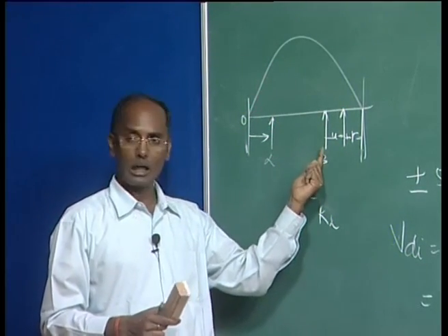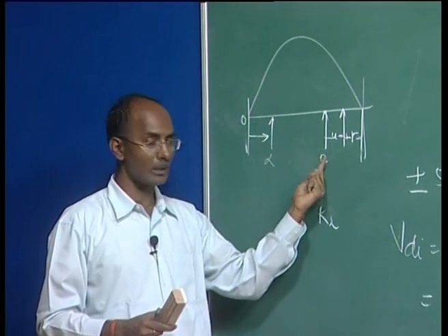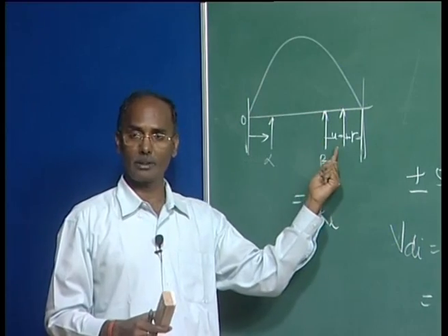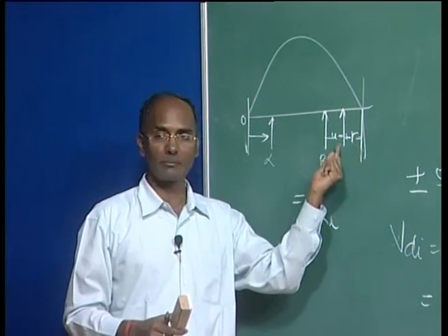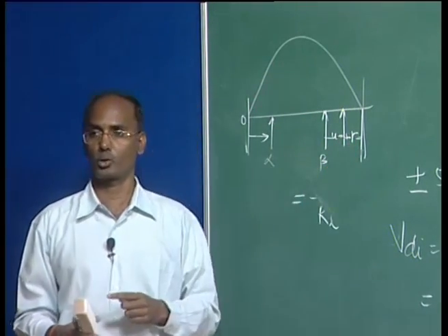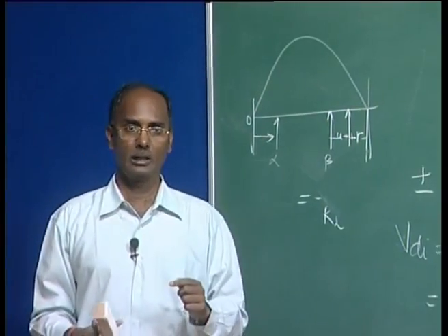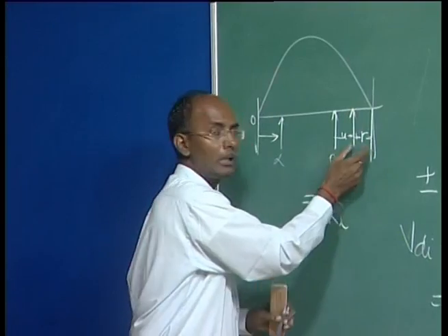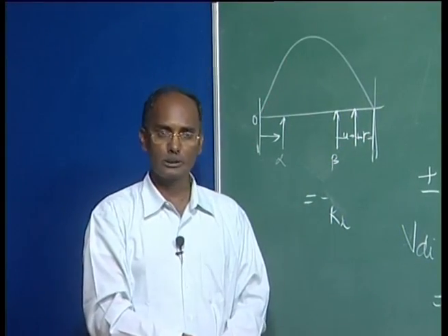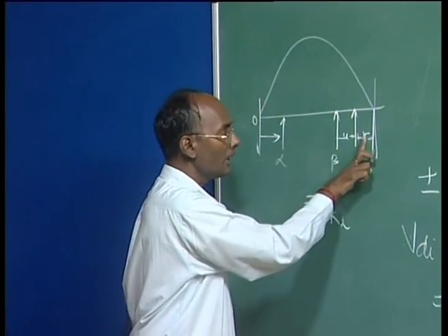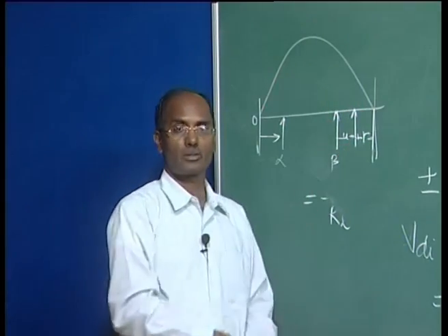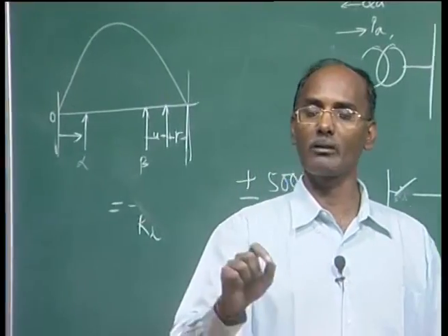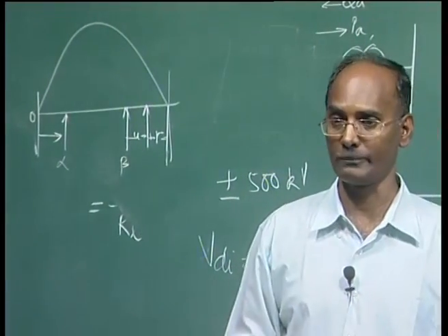So, either we can operate our inverter by knowing this value or this value, but it is always preferred to operate our inverter end with the gamma control. The reason is, as I said, if you are not maintaining this minimum gamma, there is a possibility that the voltage is reversed, means commutation between the two valves is taking place and the voltage may reverse without completing the commutation.